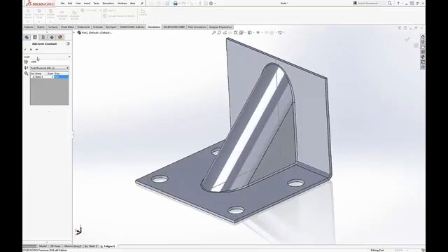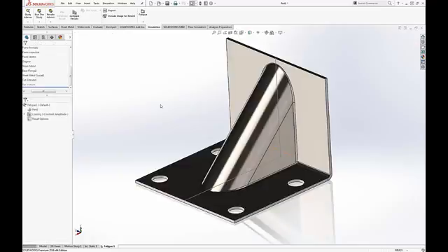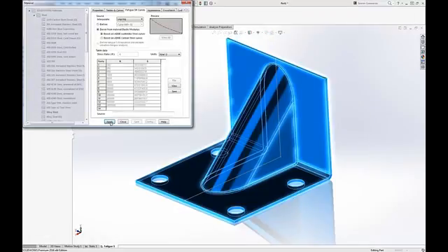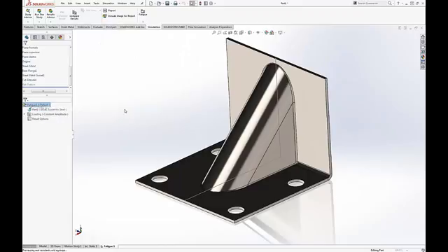We can add an event, in this case 1 million of the static event. What does it mean? It means that I will try to understand what is happening if I'm pulling and pushing this force back and forth 1 million times. So it's not only about a static analysis, but in the time frame. So here I've loaded the event. I can define the curve, and I can just run it.